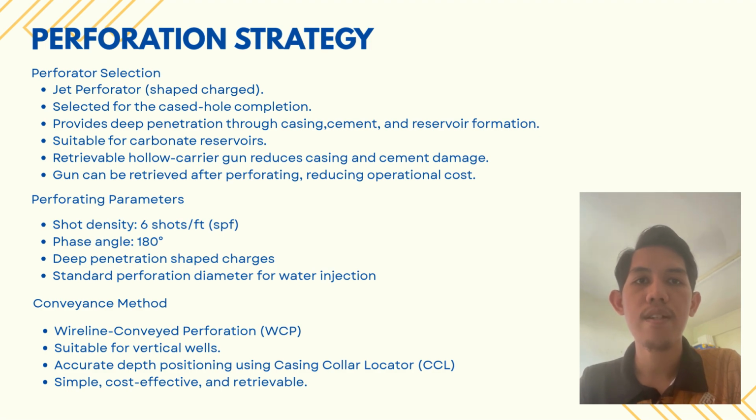We also selected a retrievable hollow carrier gun. This type of gun absorbs excess explosive energy, which minimizes damage to the casing and cement. In addition, the gun can be retrieved after the perforating operation, making it safe and more cost-effective.